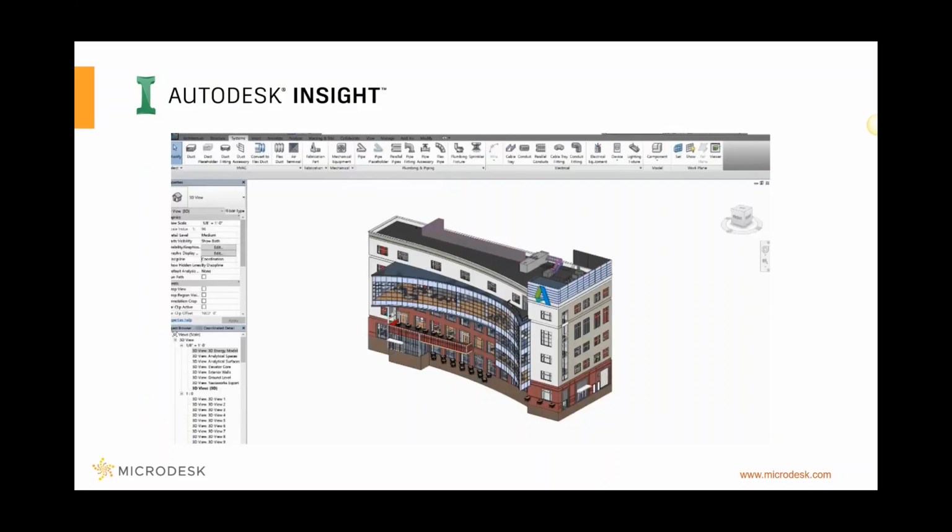It all starts with a building model, either from Revit or FormIt, which, if you remember, is also included in the AEC collection, and the physical site location information from those platforms. We can then use the Insight tool in the Analysis tab to immediately send our model to the analysis environment, where we can review information such as lighting efficiency, HVAC, photovoltaics, peak heating and cooling, and more. This information can be used to develop multiple design options and help to determine the best solution for building performance.